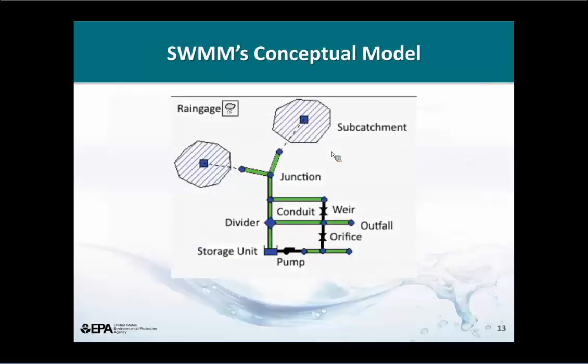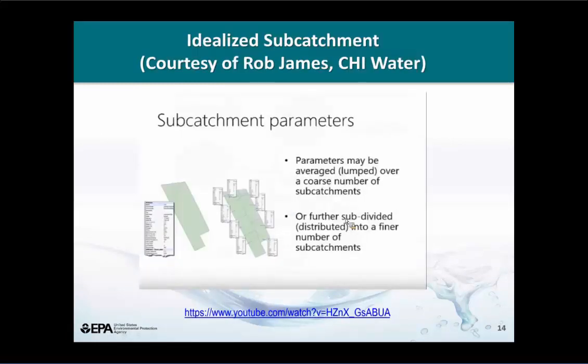Let's see. Here's SWMM's conceptual model. SWMM is modeling rain, so you need a rain gauge and you need precipitation data as well as evapotranspiration data based on temperature and wind speed. You also need sub-catchment areas. Rain is a length. Sub-catchment areas are length squared, so combine their L cubed flow. You have flow that comes from your sub-catchment area into a node, into your conduit, into the rest of your sewer system. SWMM is used for billions of dollars of upgrades for multi-decades worth of work.